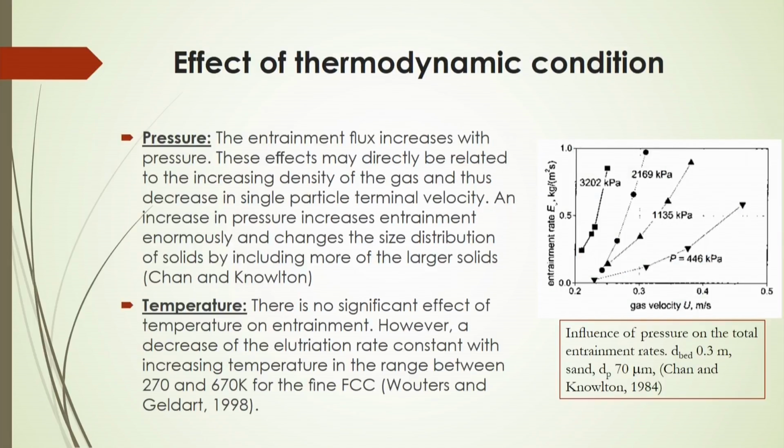Now, is there any effect of thermodynamic conditions, like pressure or temperature? The entrainment rate increases with pressure. Of course, you will see these effects may be directly related to the increasing density of the gas, and thus a decrease in single particle terminal velocity. Increasing pressure increases the entrainment rate enormously and changes the size distribution of solids by including more of the larger solids, according to Chen and Knowlton.